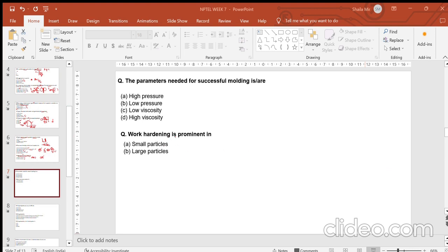Rule of mixing is a general rule. It is used for all. It is not limited to powders and their theoretical density. It can be extended to liquids. It can be utilized for determining any other parameter other than the theoretical density, whether it is volume, weighted average, or anything else. So you can calculate using that. Both of these methods are right, so there is no problem in using any of them.